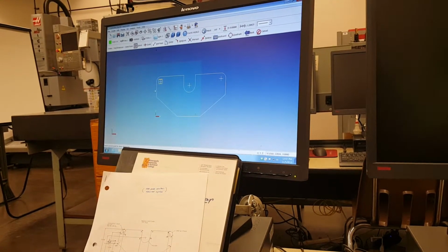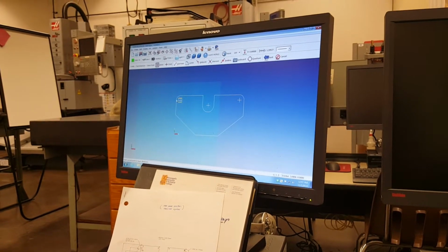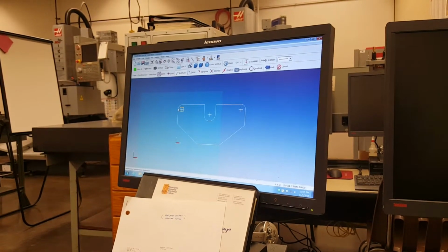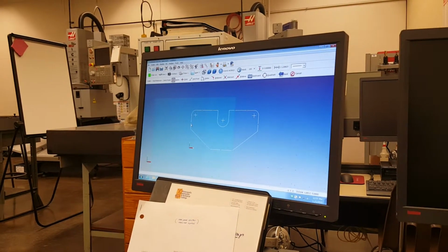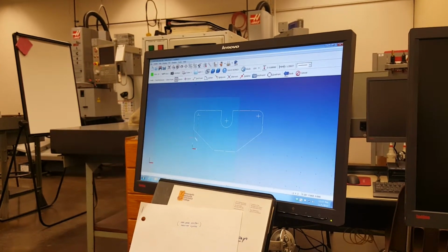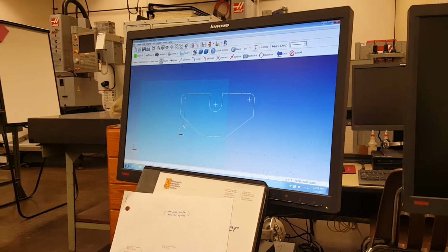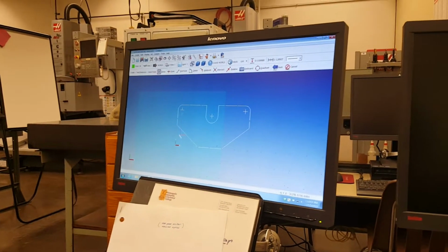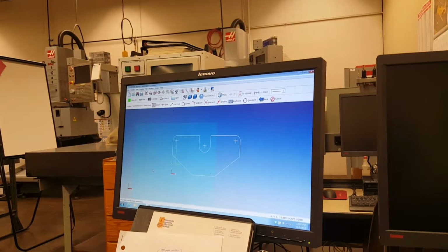Now when I say end point, if I went up towards here, it would go up to where it transitions into a radius. As long as you're below the halfway point, it's going to make that right there. And you can move it wherever you want, I haven't clicked the mouse yet. And I'll put it right there. Once you click the mouse again, it goes in.